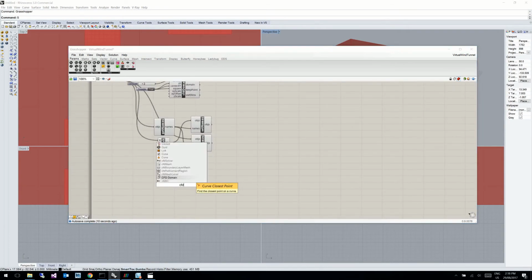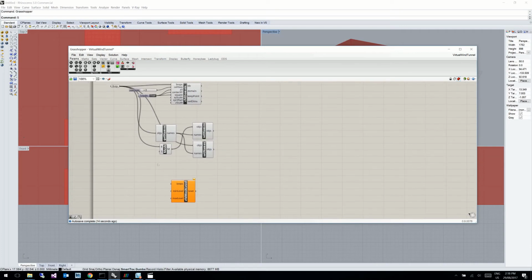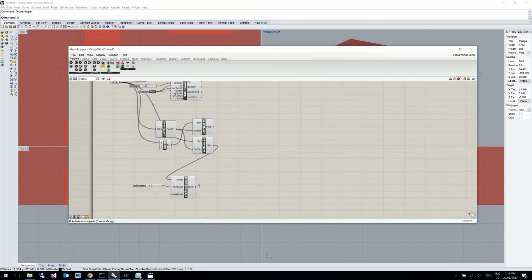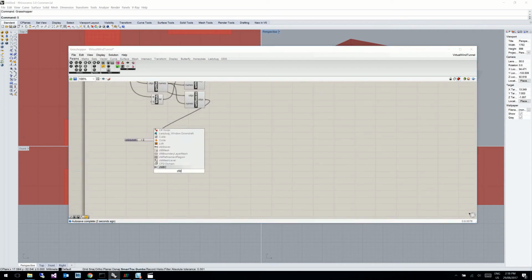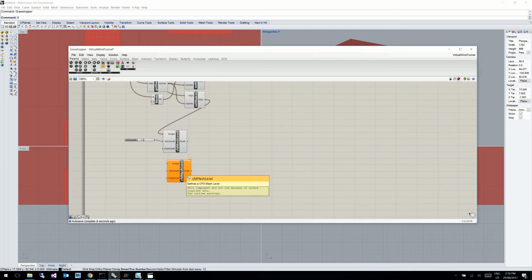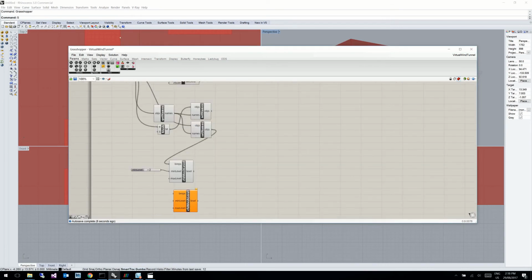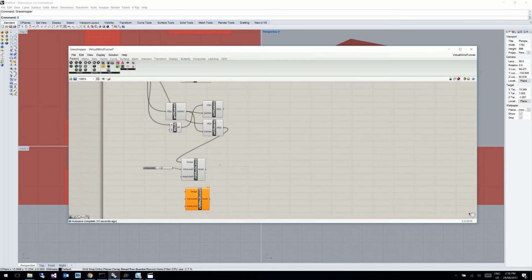Next thing to do is you want to set a CFD mesh level, and in this case we'll just take all of our BREP objects that have been named. You want named BREPs coming in there, and we'll set a mesh level in this case of say 2. You can add more mesh levels obviously if you'd like, and you can select these BREPs in a more strategic way, and the outer ones might be at a lower level than the inner ones, but for this basic tutorial, we'll just set them all to the same level.